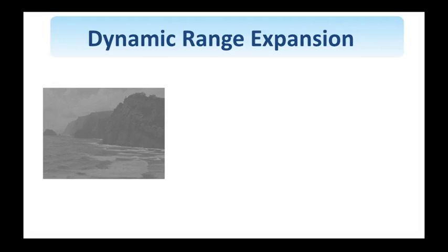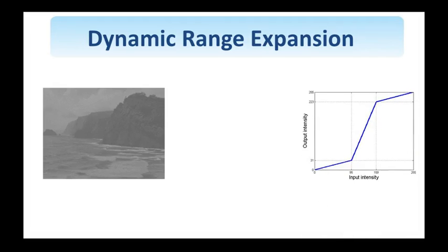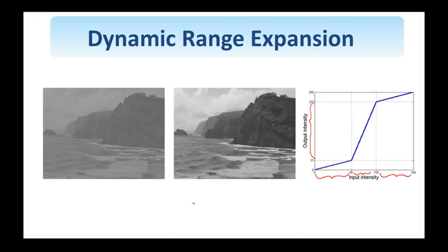So in this case, I'm allowed to use a transformation that is piecewise linear. So if I use this transformation on this image, which has 3 linear pieces, we see that I compress the low intensity values as well as the high intensity values, while I expand the values in the middle. So the range 95 to 159 was mapped to the range of intensity values 31 to 223 in the output image. So if I apply this transformation, I obtain this image here. It's clear that the definition of the clouds in the sky is much more pronounced and clear now. The waves here and the white waves and so on. It's a much more informative image as well as more pleasing to see.